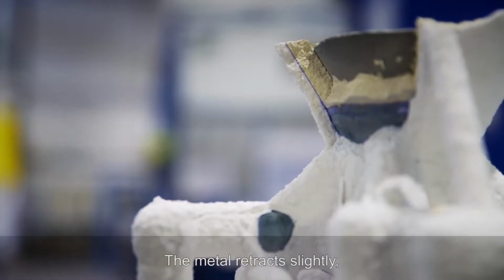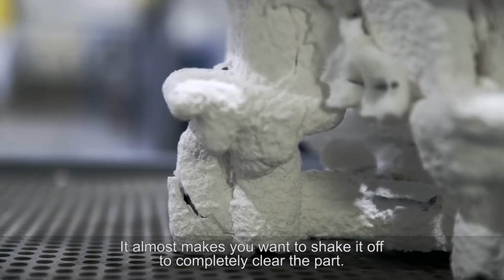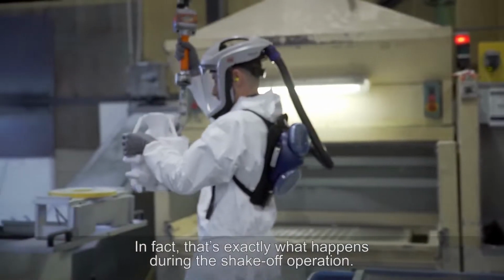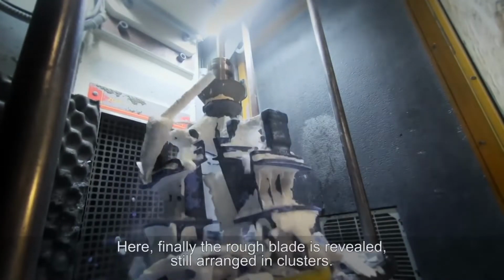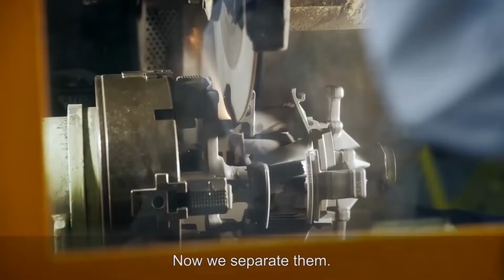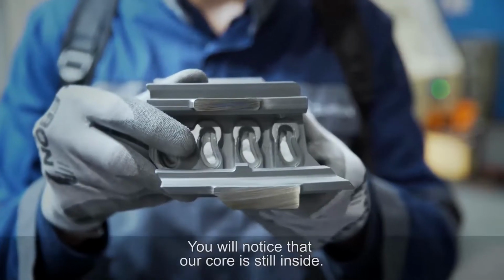The metal retracts slightly, which causes the ceramic layer to develop cracks. It almost makes you want to shake it off to completely clear the part. In fact, that's exactly what happens during the shake-off operation. Here, finally the rough blade is revealed, still arranged in clusters. Now we separate them. You will notice that our core is still inside.